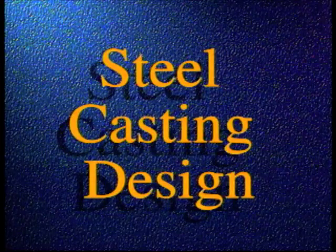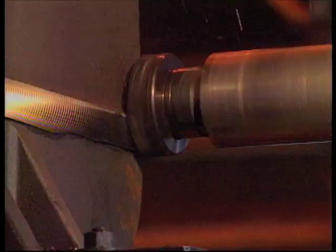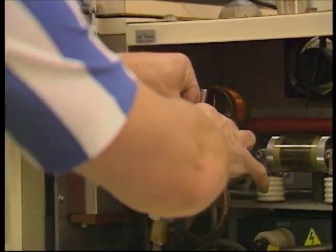There are three basic steps involved in producing a steel casting. 1. Cores and molds are made to create the shape of the part. 2. Steel is melted and poured into the mold. 3. The steel casting is removed from the mold and is ready for finishing operations, cleaning, machining, non-destructive examination, or